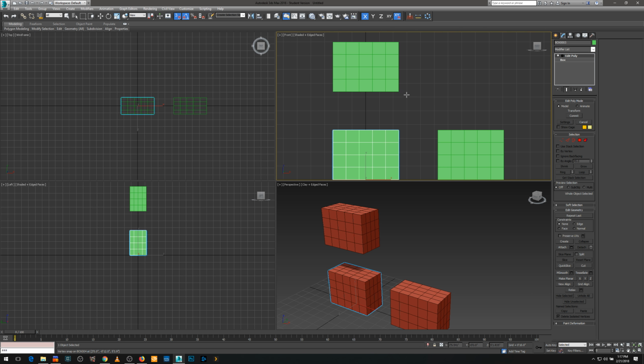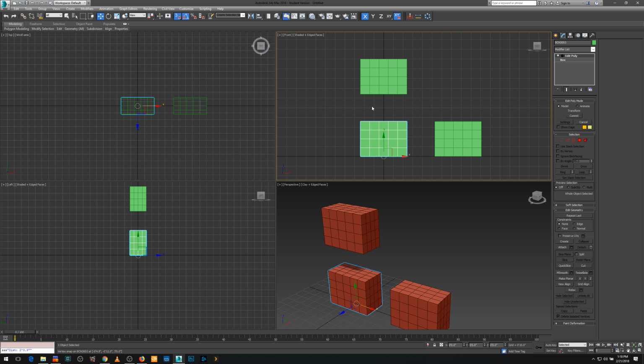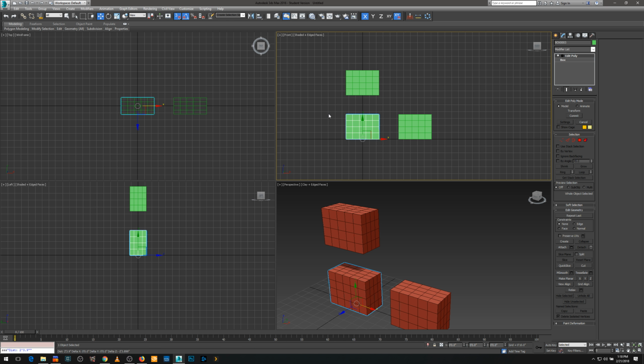Now the measure tool, or measure distance. And then, let's see, okay, here we go. So you see the little highlight, the little yellow crosshair? That means it's snapping to that point. I'm going to click once. I come down here and you see the dashed line. I'm going to click again. Down here in the MaxScript editor, it tells me the distance. 2 feet, 3.9 inches. So in case you're taking notes for when you're using multiple objects that have to be a certain part, let's say we want to build a part that bridges these two, we can use the measure tool to figure out how tall it has to be or what have you, whatever the distance is.